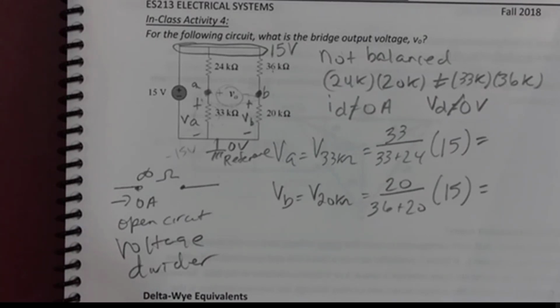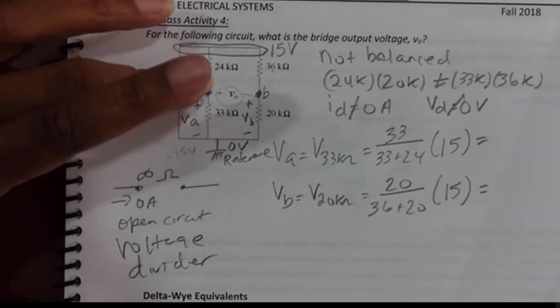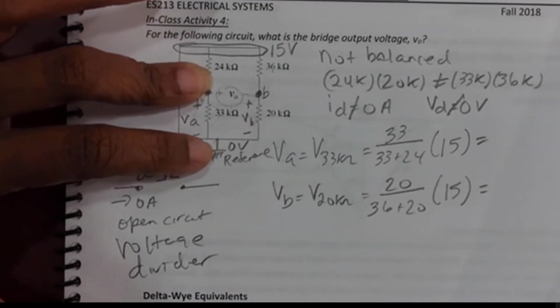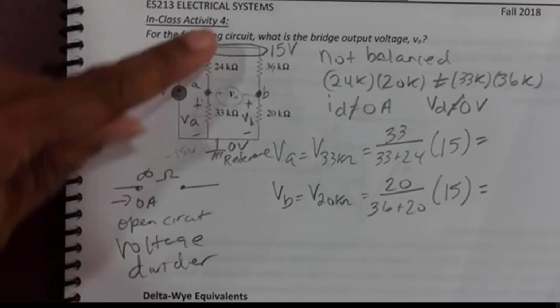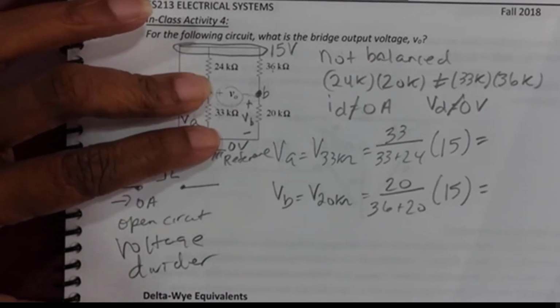No, it's because I made it the reference point, which I always make the bottom of the circuit. I don't have to. I can make that top node ground as well, right? And then it changes your answers, but the delta for the voltage is still the same, right? I'm looking for the difference between the potential here and the potential here. Even if I put ground up here, that delta would still be the same.